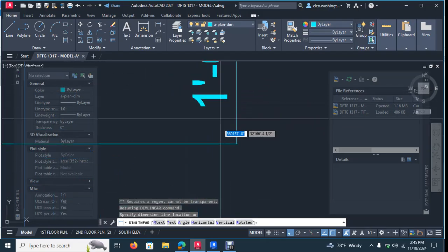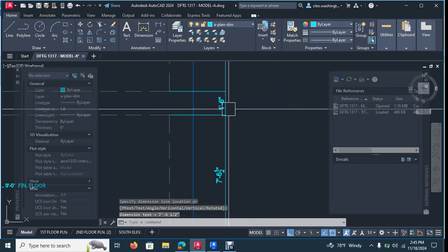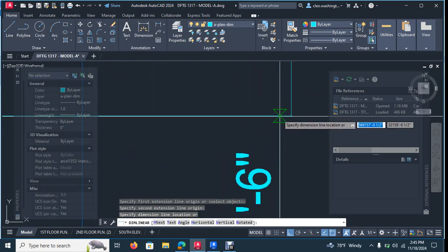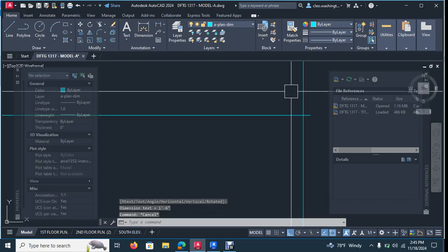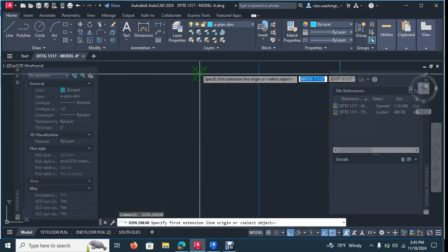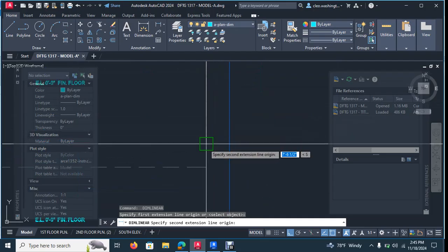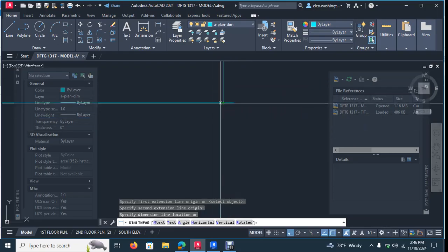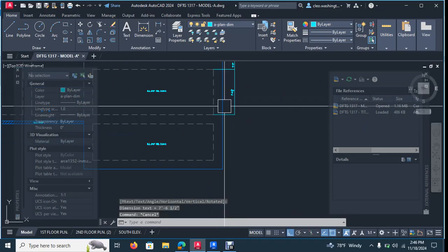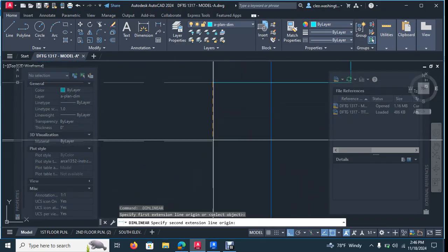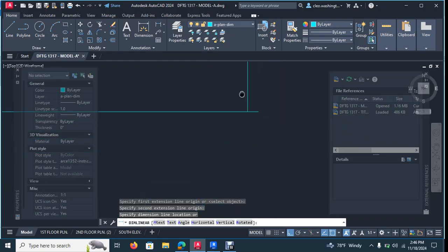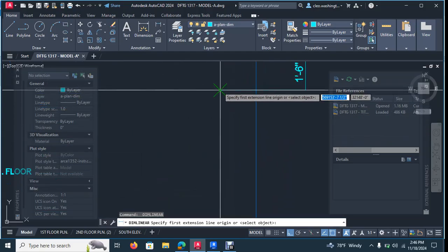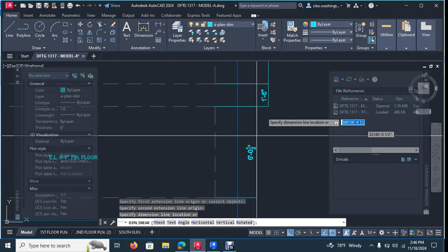And you would just go all the way around your building dimensioning your grade beams first. You want to make sure you have the proper spacing on the grade beams again, so the contractor can know where to dig the grade beams. You have to give him that dimension. And as stated, most of the time architects don't draw this, but I've had some experience drawing them. In most cases you'll just send it off to a structural engineer. Unless it's a very small project and it doesn't require a license, then yeah, you can actually just design it yourself and get this approved for yourself.